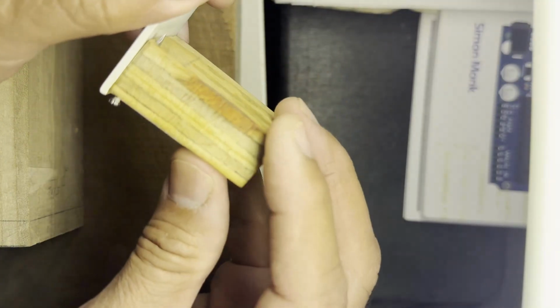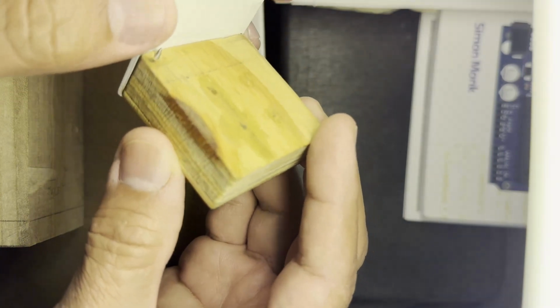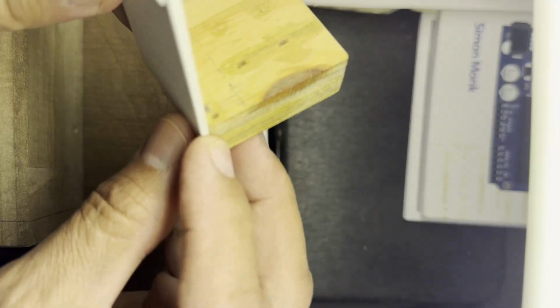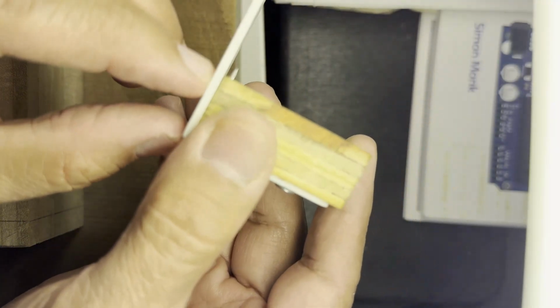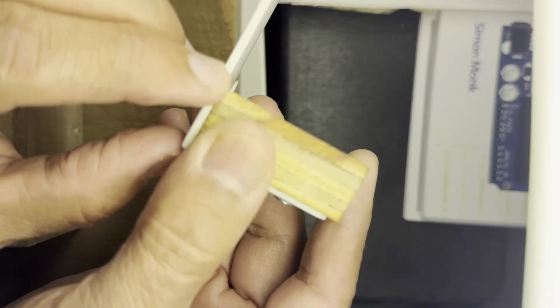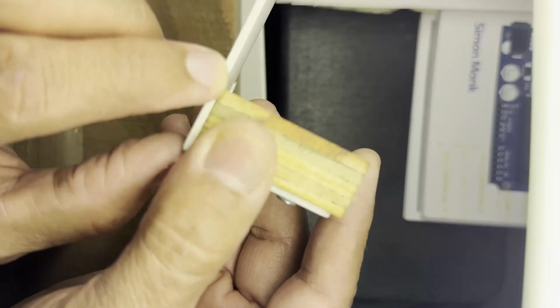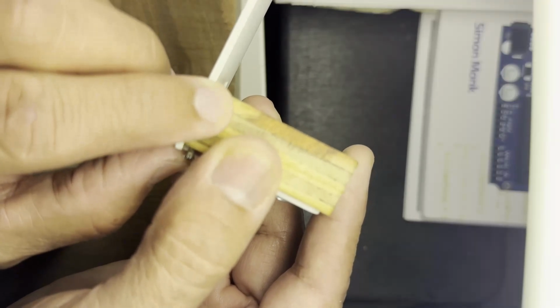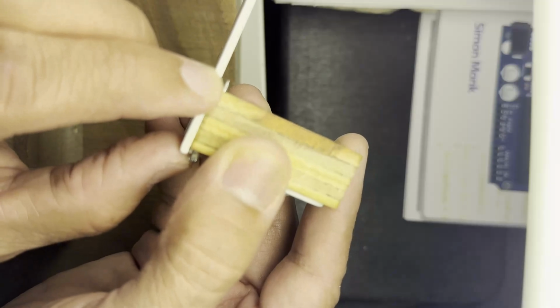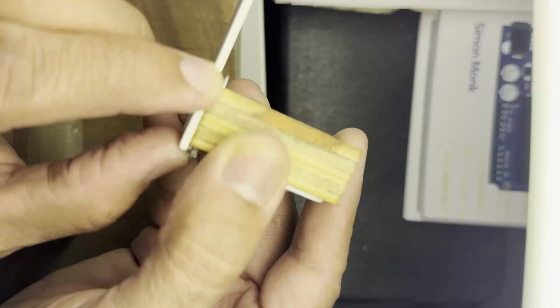I put a piece of plywood, pretty flat, and in this corner I put a scribe, and I made sure that the distance from the surface of the plate, the fence, to the tip of that scribe is exactly equal to the thickness of the rib, in my case 2.5 millimeters.